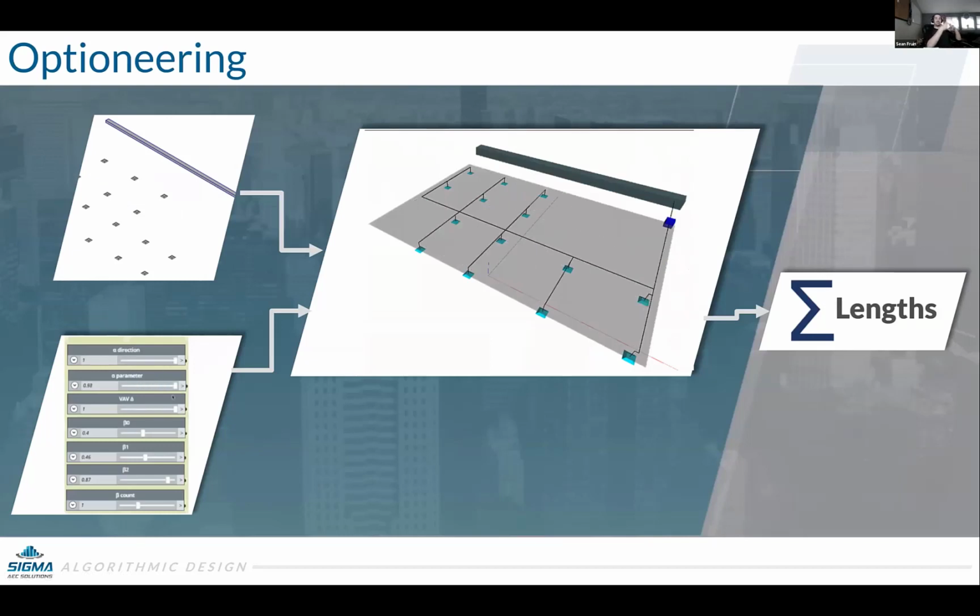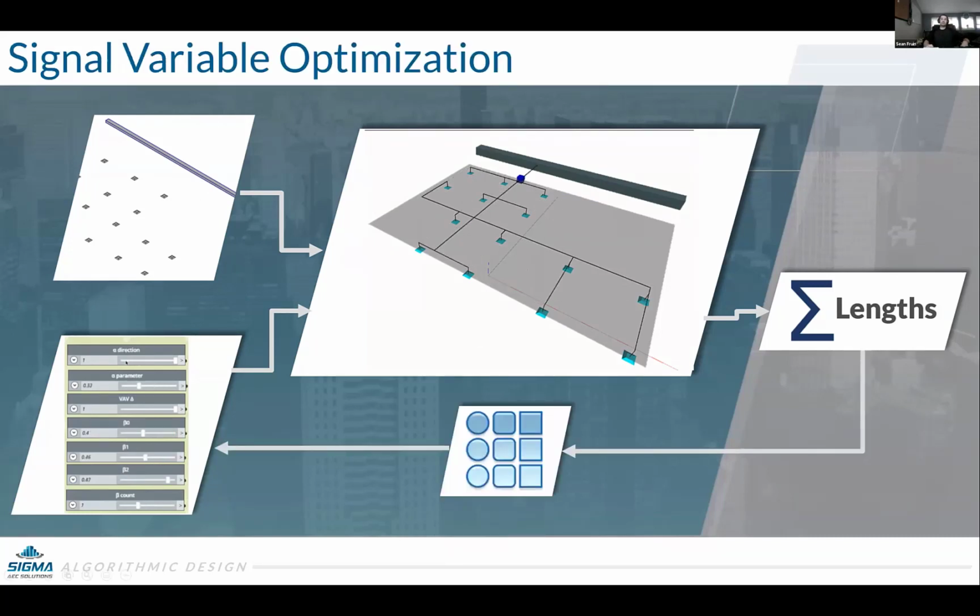Right, so then let's keep going with this idea. So now we can see how we put geometry. Another thing we can do now is start to look at layouts. Here we're just taking the main duct, and we have a whole bunch of diffusers, and we're just building a network between those. And then let's say we wanted to minimize this. We could use Generative Design in Revit and Dynamo, to even do a single optimization on it to actually minimize that length rather than just flipping through all the options at once.